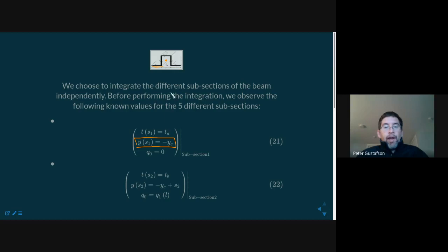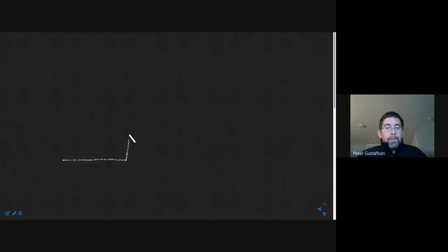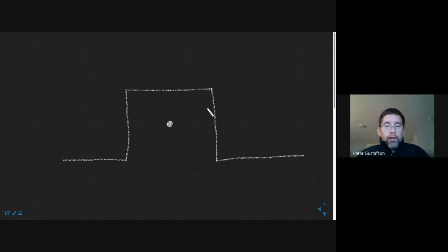Okay, it's worth noting that, and I want to make sure this is clear, because I'm not sure this came out terribly clear last time. So we said that the centroid, by sort of visual feel, we know it's basically the average location of the material, so it's going to be in the center. And what we actually are doing here is we're defining, we need to measure y from the centroid. And so what I defined actually is a local coordinate system. So, we'll call it x1, y1, which is different from xy.